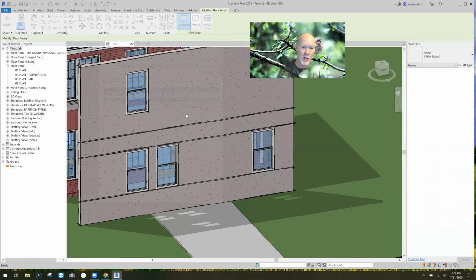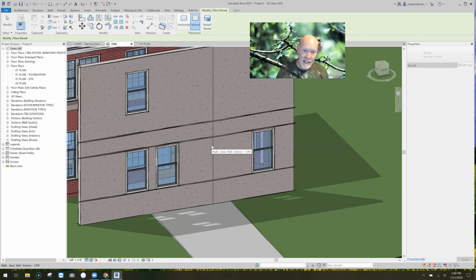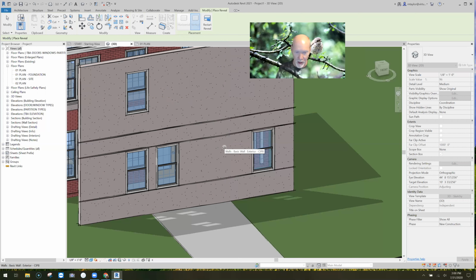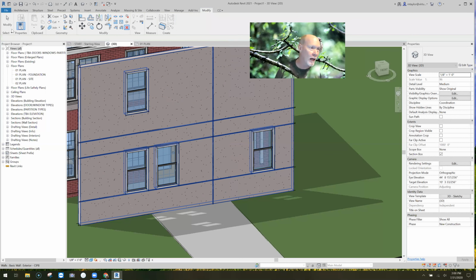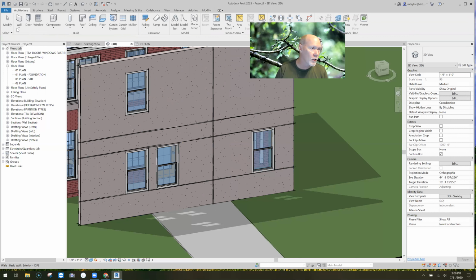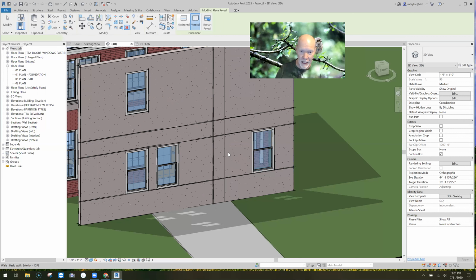Okay, so now at the top, see it's horizontal. At the top, I click on the vertical button there, and now when I click on the wall, I can place these in wherever I need them. So I placed one and I hit enter, and it pops in. I go back and get another one, architecture, wall, reveal, and I click and I hit enter, and it pops in.